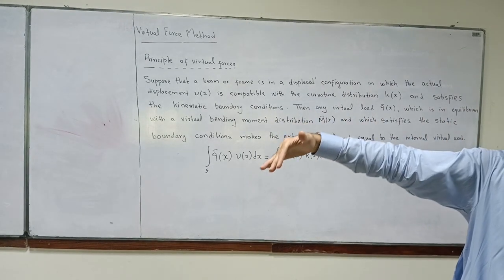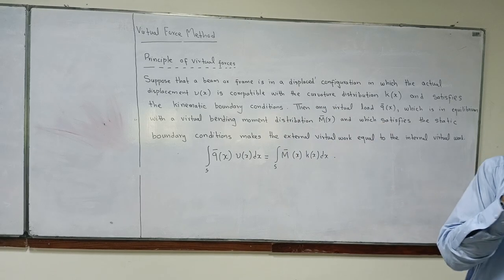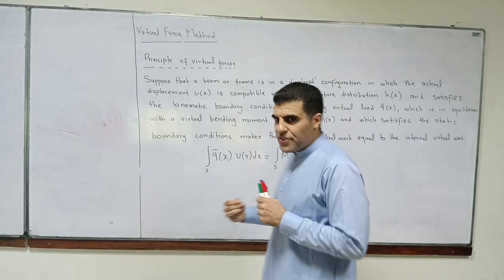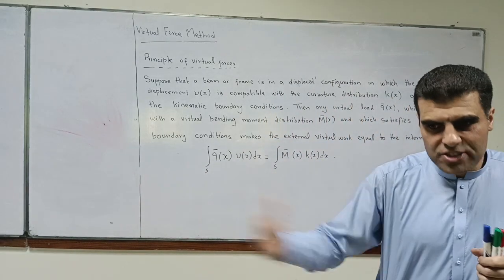All your computer analysis, whatever you do in the software, everything is based on virtual work method. So understanding of this method is very important. Moment area methods, conjugate beam methods, they are good, but they become very tedious if your number of supports increases, if you go to indeterminate structures.